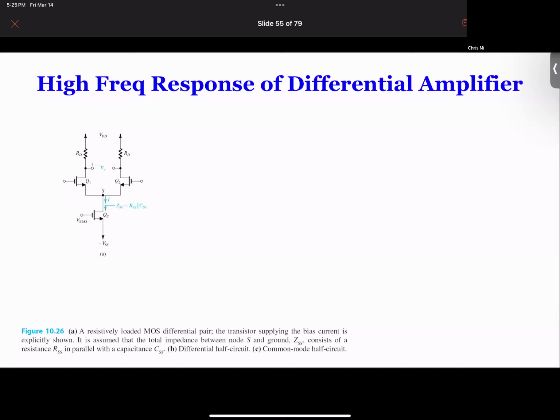Especially when we have the common mode rejection ratio, remember how we got that? Even for common mode, if the input is identical on both inputs, there's no current flowing, so we can still neglect it. Only when we calculate the common mode rejection ratio, where the input is slightly different because of a slight difference between the circuit parameters, well, we have the circuit, we cannot neglect it.